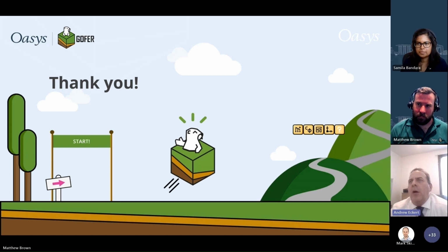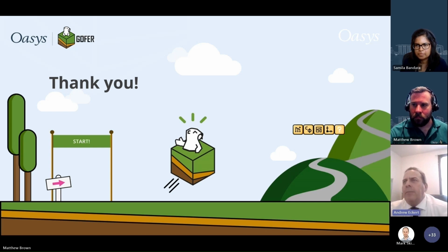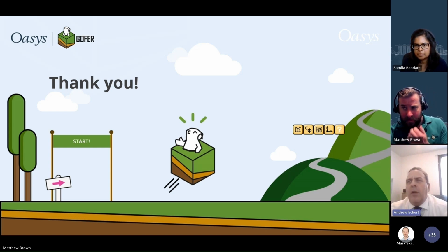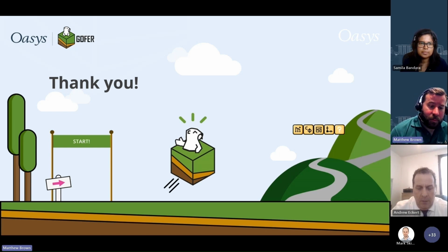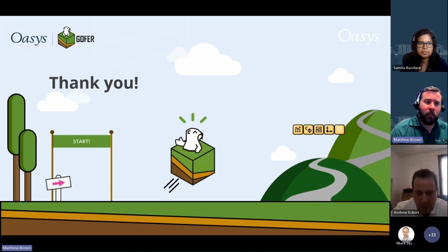And can it also model geogrid or vertical drains? So vertical drains can be modelled, again, explicitly with, I suppose, thin soil blocks with drain material to dissipate those excess pore pressures. Geogrid elements are another very high priority thing on the roadmap. So watch this space, they'll be coming soon.